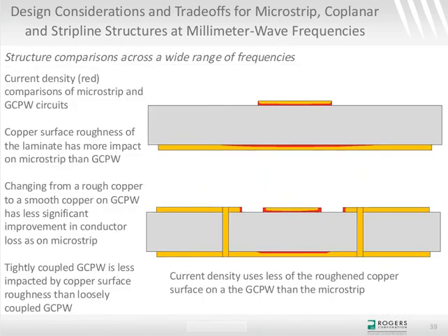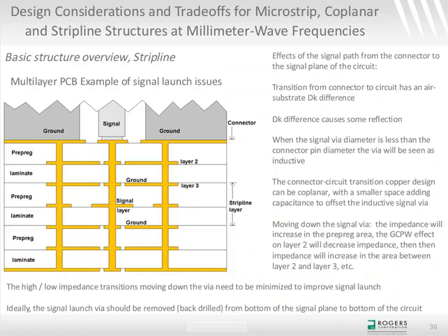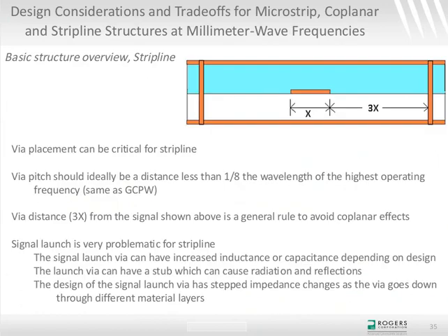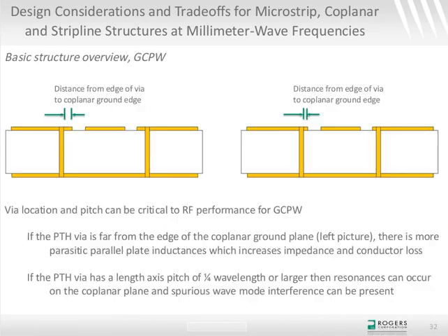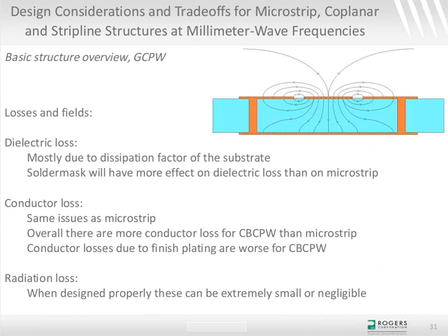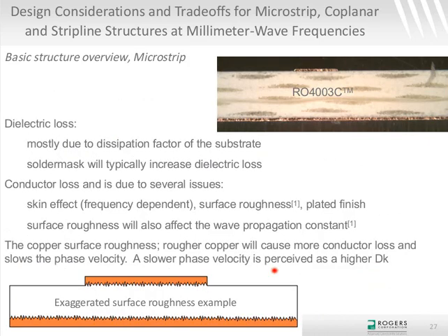Yeah, the process dielectric constant is as we make the material and we're controlling our process. The design Dk is really what should be used. And that goes back to what I said back here somewhere, where the copper surface roughness affects the phase response. A rougher copper will slow it down, a smoother copper may be a little faster, and that slower or faster phase response relates to how the circuit perceives the dielectric constant. So that's what the design Dk is trying to account for.